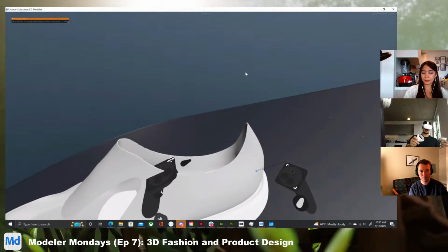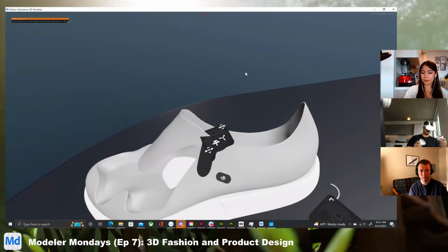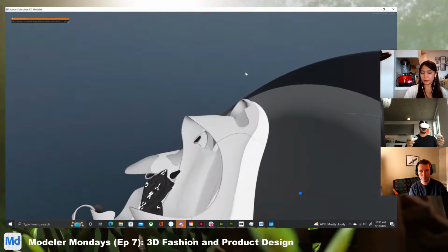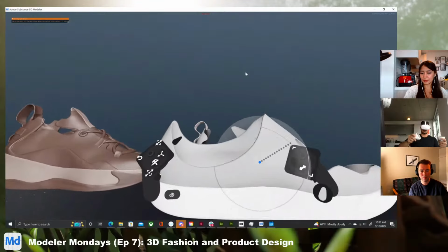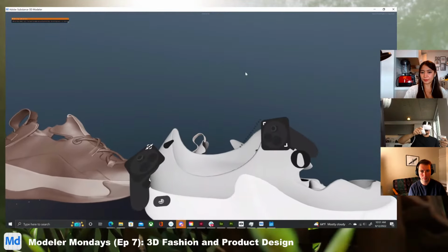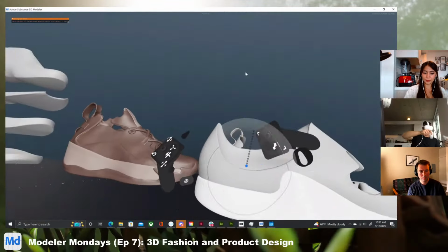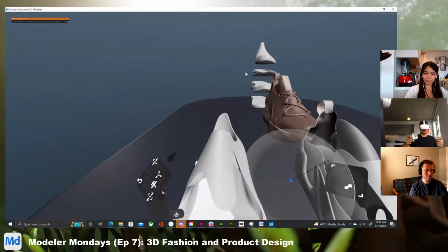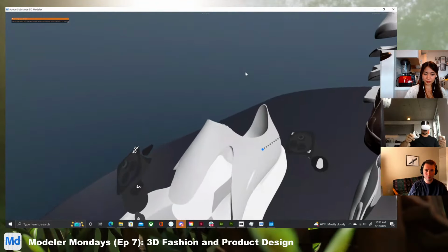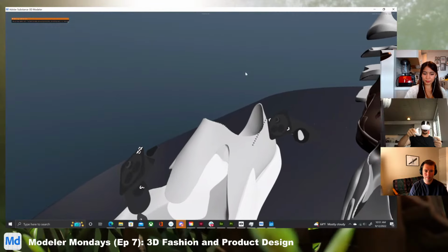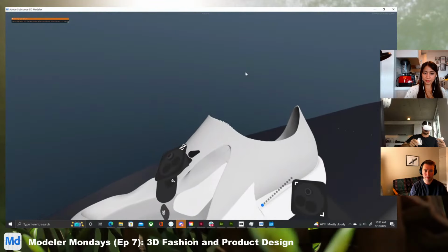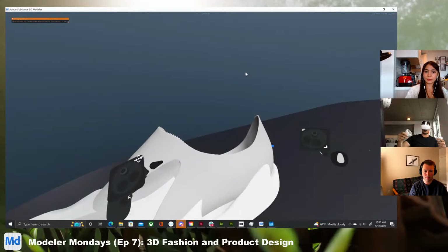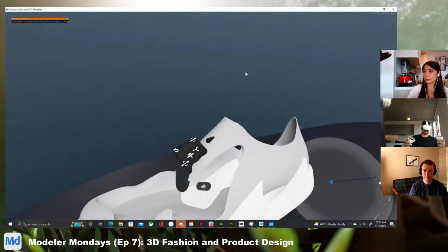For something like that, I'll link layers and have everything linked and live, so I can make modifications to everything really quickly. For the most part, with the upper or the tooling, they're all unique components, so I don't really link them too much, because I know they're going to be edited and modified pretty drastically. So I leave everything separate.